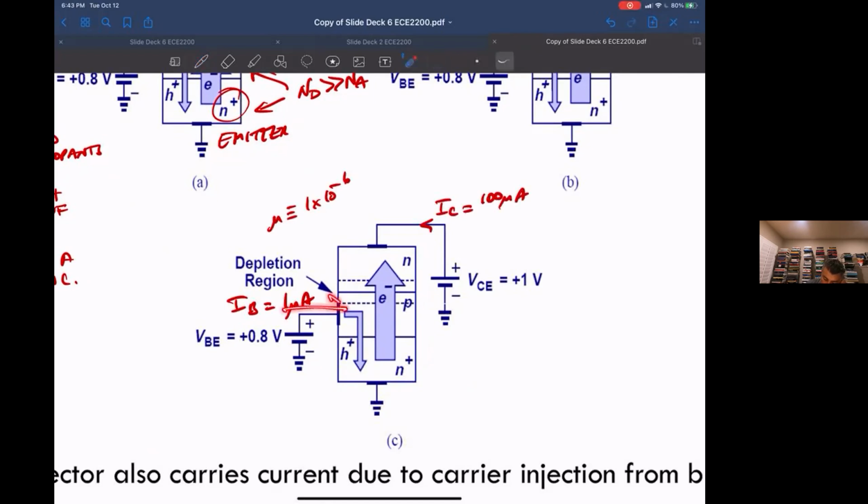Okay, so you put a small current into this control node. You can think of this base as the controlling element. So by putting a small current here, you can get a very large current at the collector. And then, if I sub B is 2 microamps, this collector would be 200 microamps, and so on. So you've created a situation where this point is not directly connected to either one of these points, but it can control the current through these points.